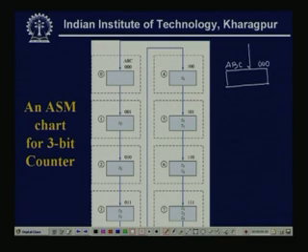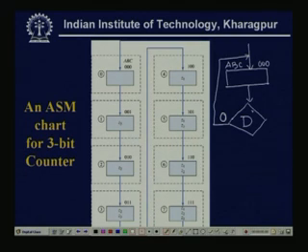So, it has one entry point, this is my initial thing. Now, it has one exit point, and now I am putting here one decision symbol, say called decision symbol D. Now, if D is false, means if it is a 0, then again it will start, or it will be in the initial state only. If it is 1, that means this is another exit point, then only it will go to the next state or the other state symbol coded as 001.